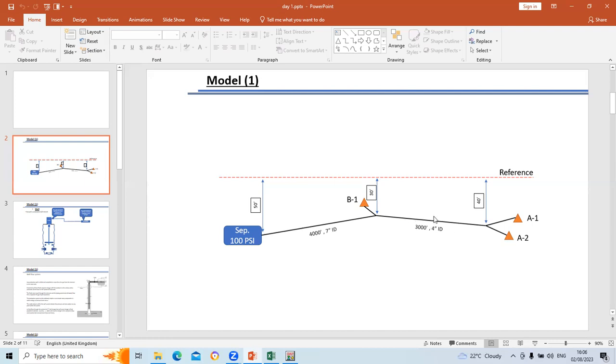If we have a change in the flow line condition, it will definitely affect the pressure at the node, which in some cases may be the wellhead pressure. And once the wellhead pressure is affected, the entire system is affected. So a change in the flow line or in the pipeline system will affect what happens in our individual well, and a change in the individual well will affect the entire system.